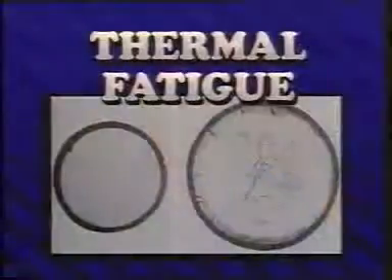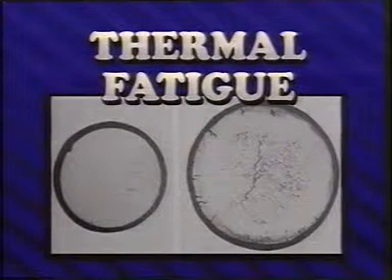Thermal fatigue is a residual stress effect. It is caused by simultaneous mechanical restraint and repetitive thermal changes. The thermal expansion is caused by a local temperature increase. The expansion acts against a restraint, usually the harder, stronger, cooler metal adjacent to the heated metal.